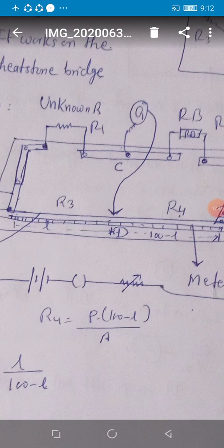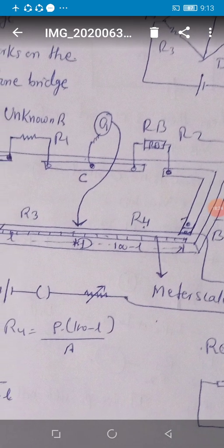Next, say you have another resistance of 5 ohm. Now you take out that 3 ohm and connect 5 ohm in place of R1. Again you find out the balancing length and experimental value. You will get another value near to 5. Now, student, you connect 3 and 5 in series. Series means one-to-one connection. One terminal is connected together, and the ends of those 2 terminals you connect at R1. Means in R1 you are connecting 2 resistances in series. Again you find out the balancing length and you will get the value of R1. Remember, you are getting the series combination value.